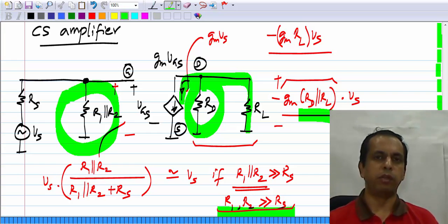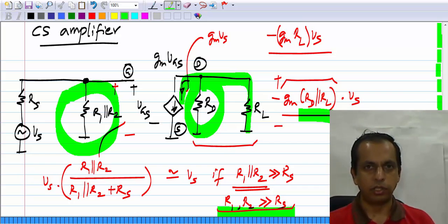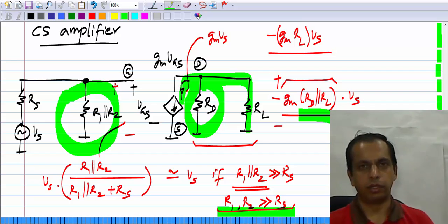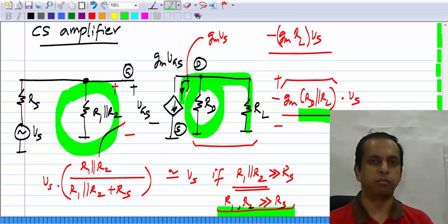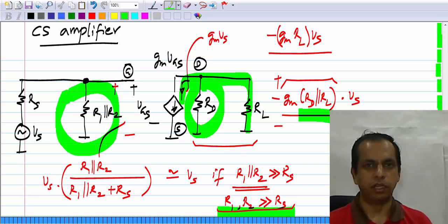So, this should give you a pretty good idea of, first of all, if you see a new circuit, how to start analyzing it, and also all the practical constraints that come about. Okay. Although our functionality is the small signal incremental functionality, and we wanted a gain of minus gm RL, because of the biasing components, we can have some reduction in gain or some effect in different circuits. Okay. All these have to be analyzed.